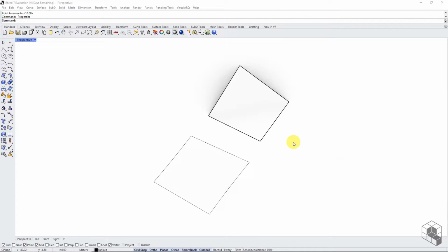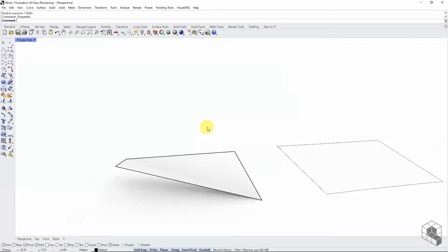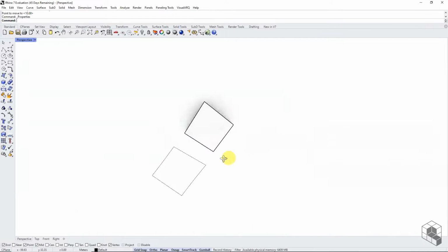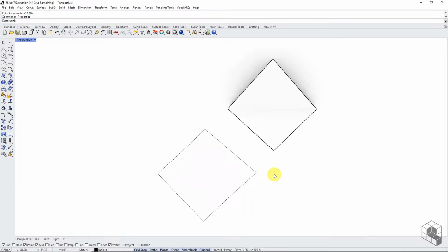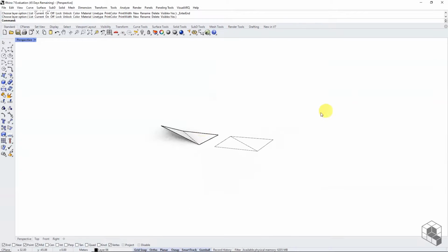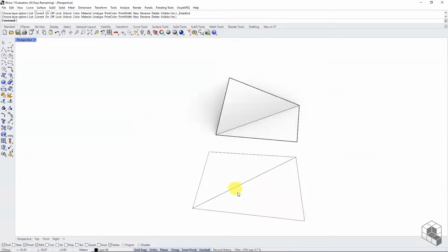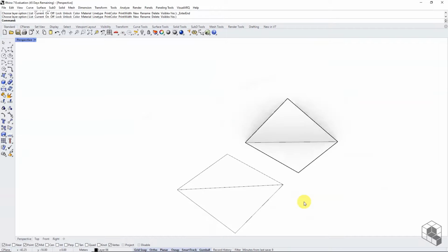In this video, we will cover the face triangulation process. Quad meshes or 4-point surfaces are not always planar. Most of the quad faces generated in the previous chapter are non-planar faces. This leads to minor variation in the unrolled geometry, which ideally should not happen. Triangular faces, on the other hand, are always planar. Hence, triangulating quad meshes before unrolling is an effective method of ensuring proper unrolling of strips, without geometrical deviations.